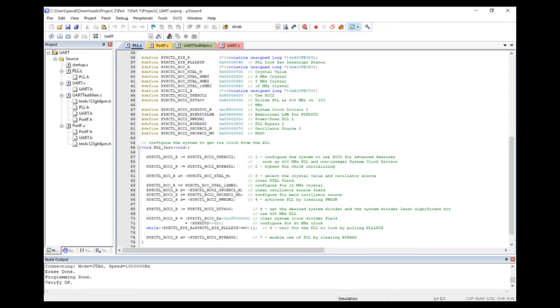The PLL.C file utilizes the onboard crystal to enable a clock and set the bus frequency. This module is required to use timers effectively in the grand scheme of the project. The bus frequency is set to 50 MHz. All timers and interrupts on this project will use this designated frequency.